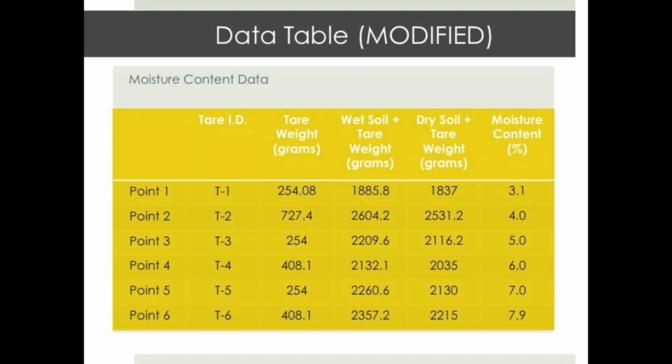Here are the results of the modified Proctor moisture determinations. Notice the optimum moisture content is at a much lower value. This is due to the difference in material. The crushed rock particles are larger than the clay sand and become saturated at lower moisture contents. Smaller particles have more surface area and therefore need more moisture to become saturated.